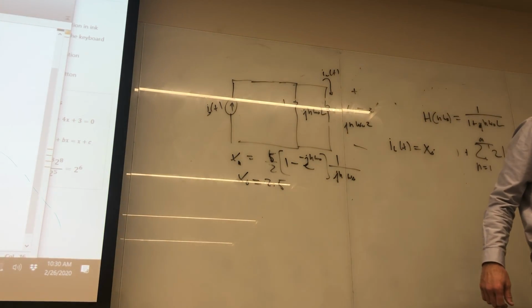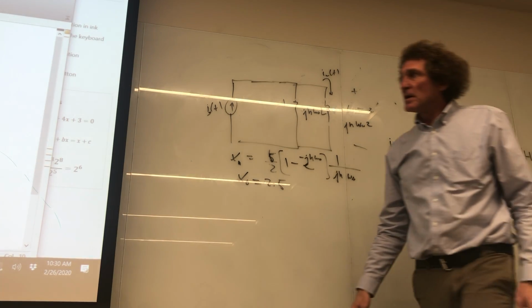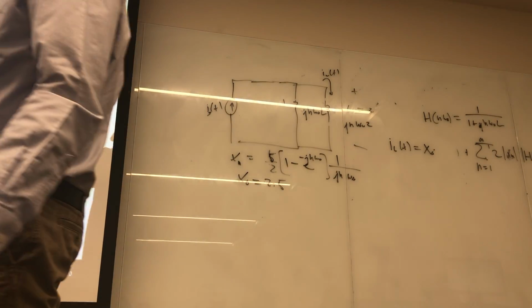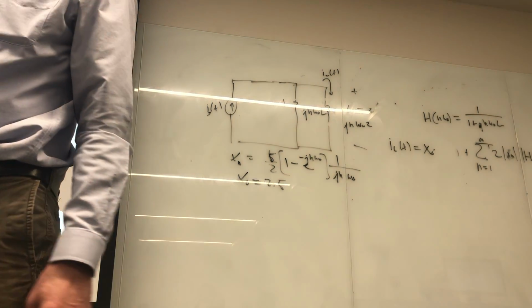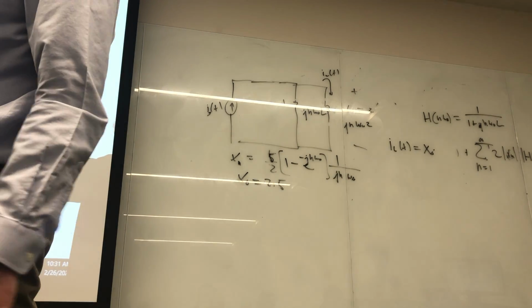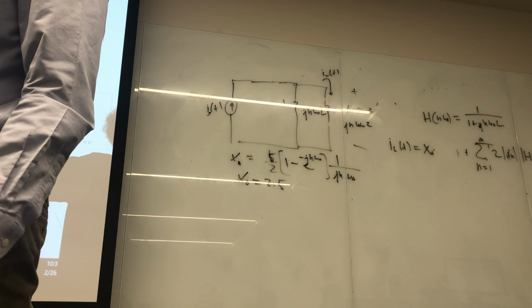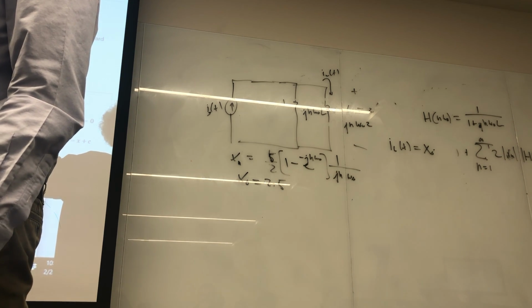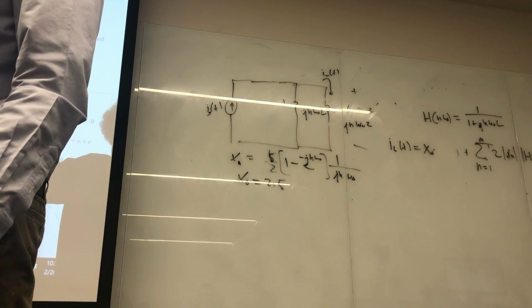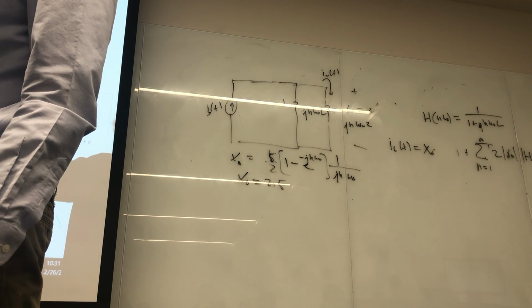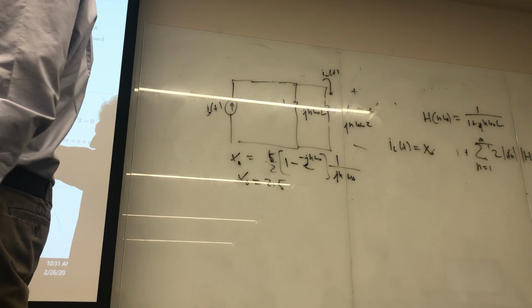But all the constants that I'm going to be using, possibly using, I normally put clear all, close all, CLC. That gets rid of it, wipes the slate clean. There's nothing there that it can mess up by looking at a piece in memory from something else that's resident there. Because a lot of times when you're using MATLAB, you're doing 2 or 3 things, and you don't know if you used L 3 or 4 other places, and so now you clear everything.